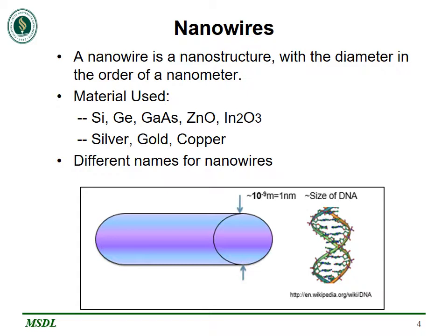Now depending upon the size of nanowires, different names are assigned to them in the literature. One is the whisker, that is a one-dimensional structure ranging from several nanometers to several hundred microns. The other is, as we know, nanowires, that have a large aspect ratio of greater than 20, and the others are nanorods, which have a small aspect ratio less than 20. Then we have the nanocontacts, that are short wires that bridge between two large electrodes.